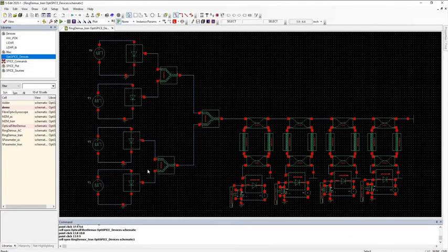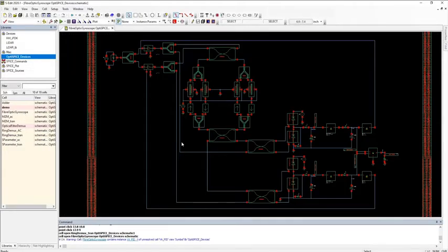One of the main advantages of OptiSPICE, as I mentioned before, is the ability to do electro-optic circuits, and specifically, it is very good at handling feedback loops. So this is a relatively large design for simulating a fiber optic gyroscope. So what happens here is we have forward and reverse traveling signals in this ring resonator in the middle. And then the frequency shift due to the rotation can be calculated using balance detectors and a control circuit.